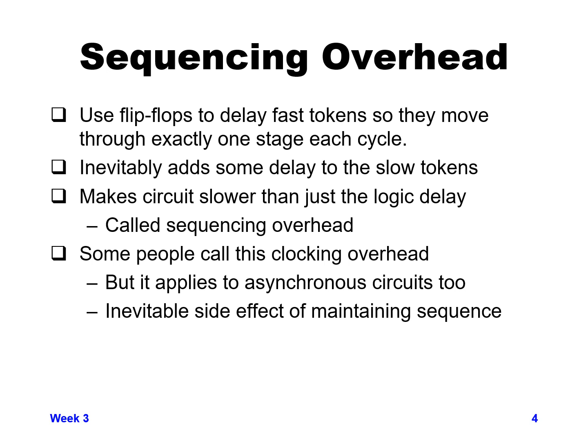And so any combinational logic path that's really fast is sitting there waiting at the input to a sequential or flip-flop element, and any ones that move slower will wind up changing just as they get to the flip-flop that is trying to sample it.